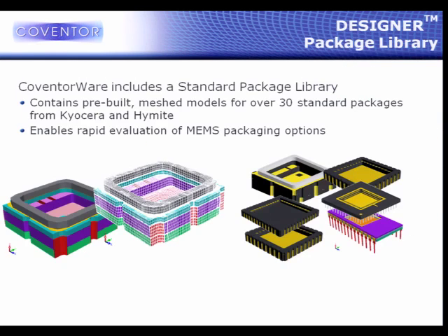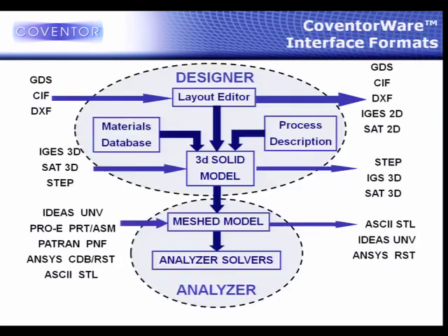Also with Designer, there's a standard package library with over 30 packages from Kyocera and Hymite. Each one has the solid model pre-built and pre-meshed. So for things like choosing a package, this can be helpful, or looking at the effects of the package deformation on the anchors of your MEMS device. This is a quick way to get started.